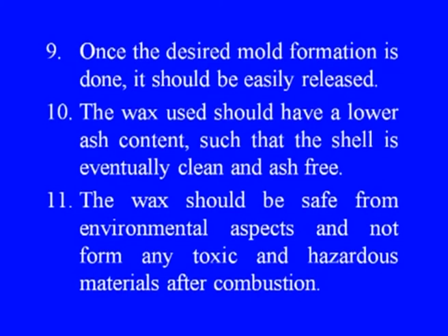Another important point. Number 10, the wax used should have a lower ash content such that the shell is eventually clean and ash free. As we know, in investment casting, the pattern is invested or lost. Therefore, if during the process ash is produced, then it might add to the impurity in the cast product itself. Therefore, it is desired that the wax should not leave behind some ash as the remaining material.